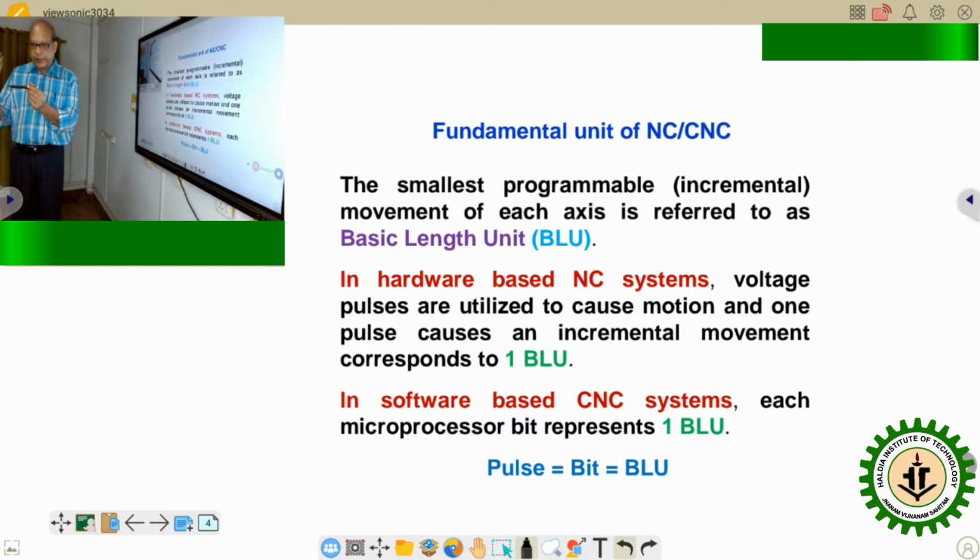If you would like to take it much closer, then say 45.86, that means 2 decimal digits we can capture. Whether the CNC system or the NC system can understand these 2 decimal digits and implement them as far as displacement is considered. If I think about 45.005, it may be too fine, which the system neither can understand nor implement.